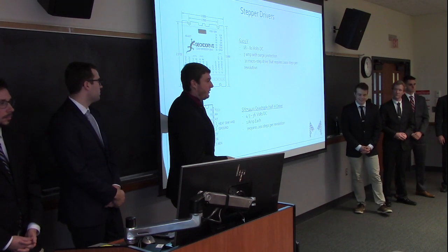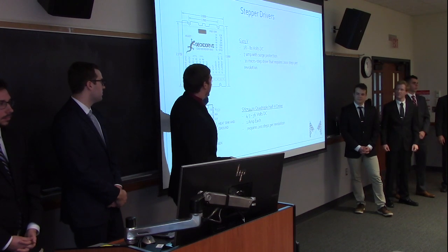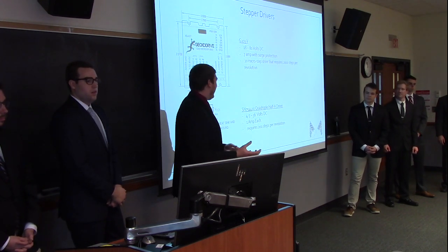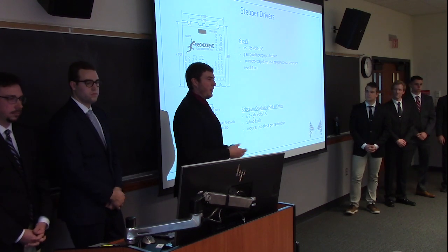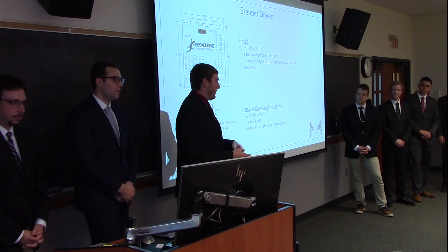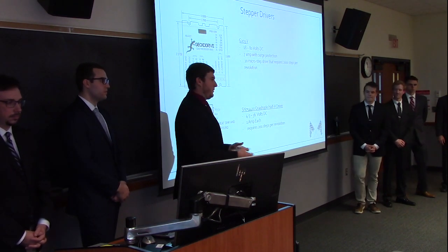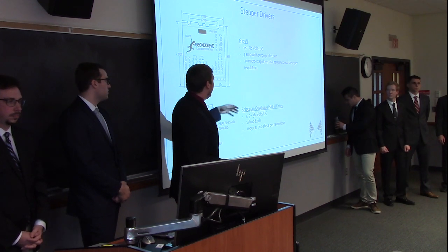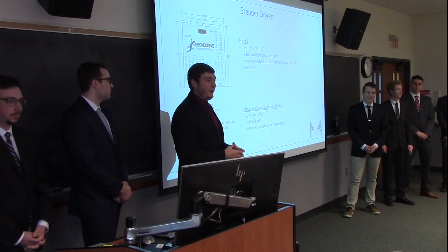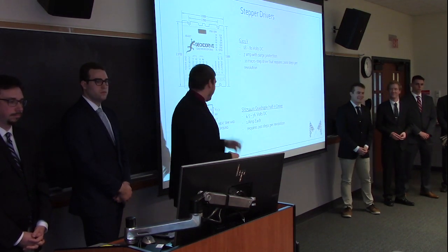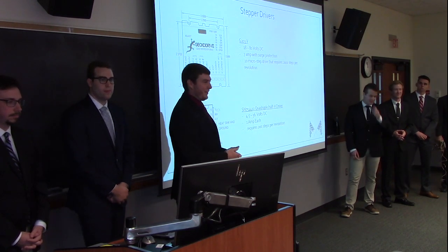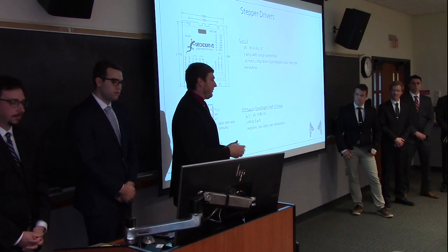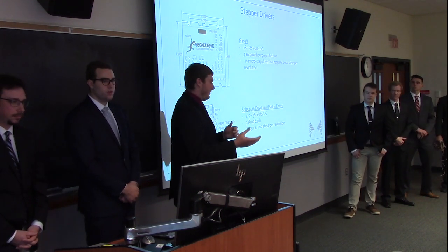Versus a newer driver that we were working with due to heating problems of the chips overheating here, which takes 18 to 80 volts. As I said, ours wasn't getting up to that voltage, so what we would have to do is use a boost converter for this. The only issue with that is adding another piece of equipment always adds another piece of failure that your product could have, though it seems like that is the approach that we need to go with. It takes up to 7 amps, which is fine with our motor, and has surge protection. The V in the name actually stands for vampire because it's literally unkillable, is what they say, which, whenever you're having issues with a piece failing, and find something that's unkillable, that's usually pretty good. This is also a 10 microstep driver, so that allows 2,000 steps per revolution, which gives you even more ratios that you can achieve.